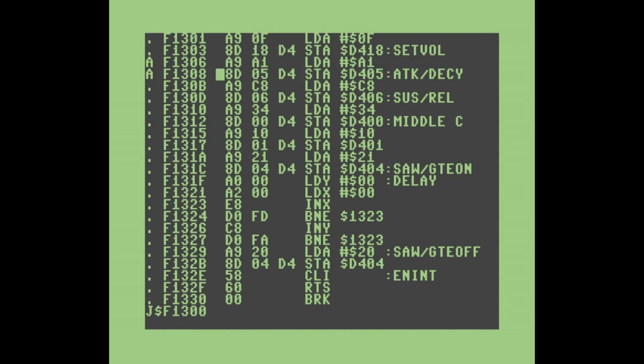That was pretty easy, but what does it sound like if we use a long attack and a long decay? Notice how our program is finished, but the sound is still playing. This is because we haven't disabled voice 1's oscillator, but instead gated off the sound, and the ADSR envelope generator is still running.